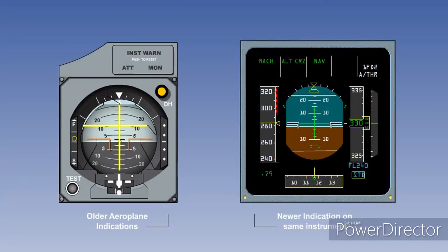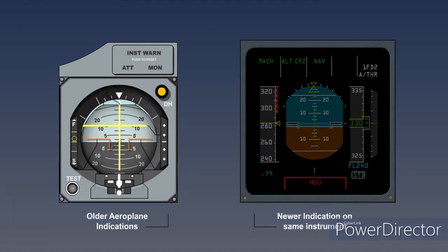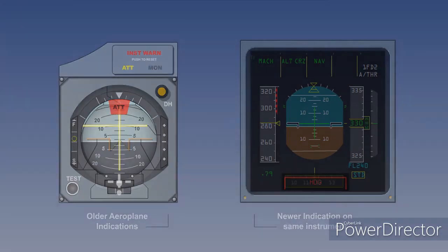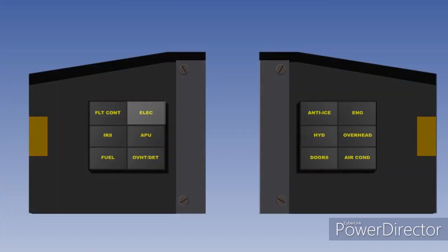Depending on the aircraft type, visual alerts will be depicted in one of two ways, either on electronic screens, as we have already shown, or as lights and/or flags, which is normal on older aeroplanes. Master warning and caution lights, also known as attention getters, are also provided for each pilot to attract their attention to problems that require their immediate attention, and located so as to be clearly visible during a normal instrument scan. In older aeroplane types, these are accompanied by a master warnings panel, where the warnings are placed in a rational order.